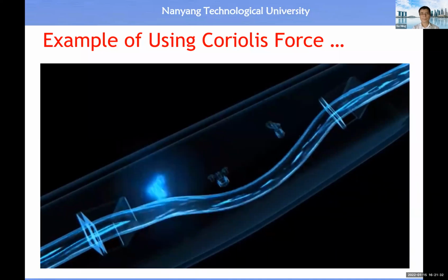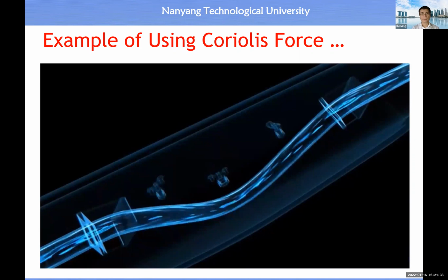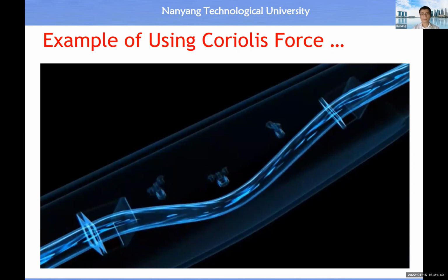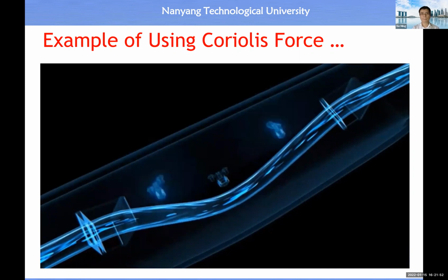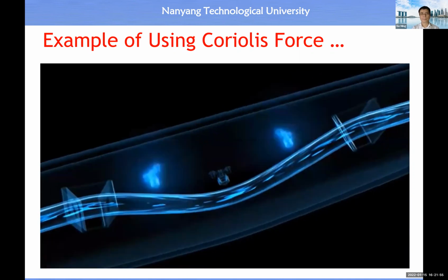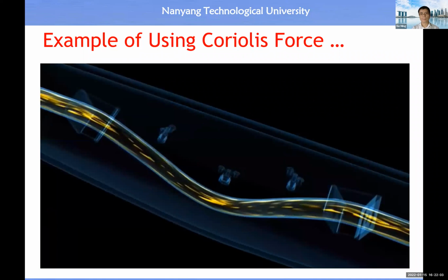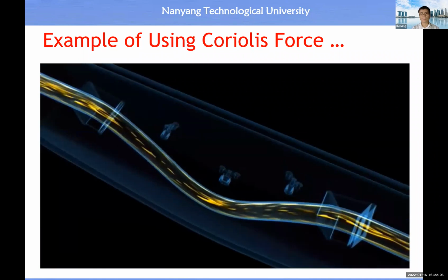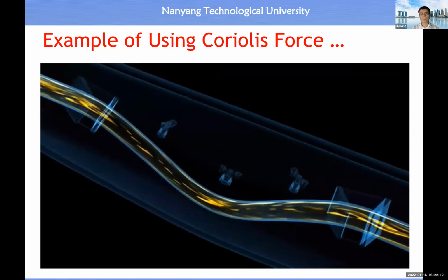It can also be used to simultaneously determine the density of the flowing fluid. To do so, the sensors also register the oscillating frequency. In other words, how often the measuring tube moves back and forth in 1 second. From the animation, it's clear that a tube filled with water oscillates more frequently than a tube filled with honey, for example, which has a far higher density. Thus, the oscillating frequency is a direct measure of the fluid's density. Both the density and the flow are determined simultaneously but independently via the tube oscillation.